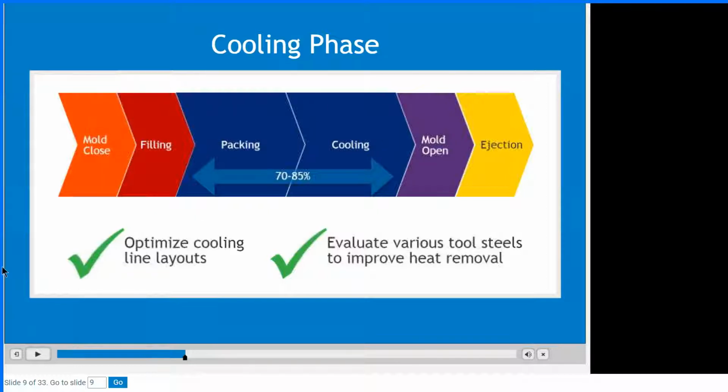So during packing, the material cools as well, of course. And so we need to take care of understanding the packing phase and cooling phase as being the overall driver of the cycle time, and therefore we need to pay attention to these two phases during the processing.